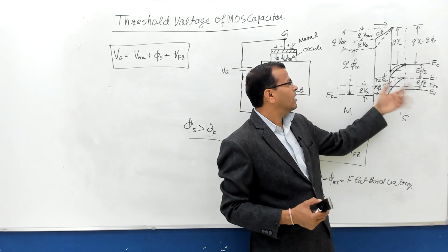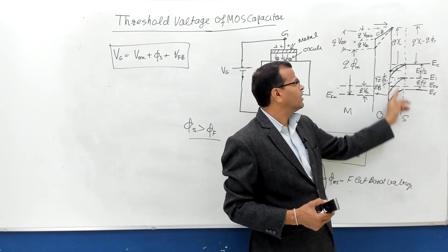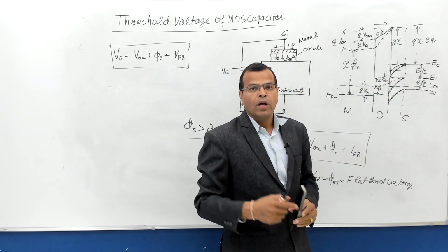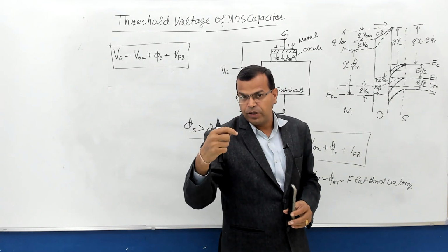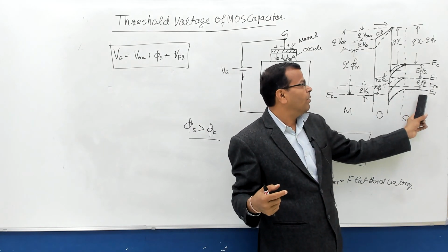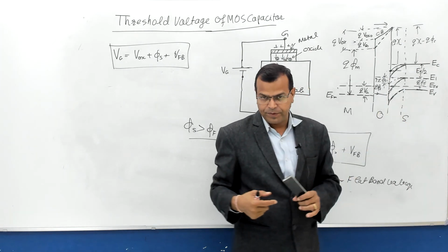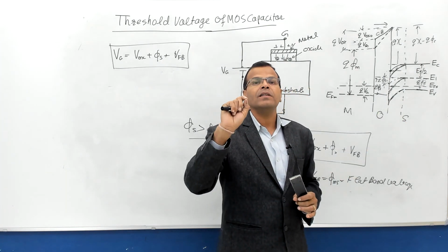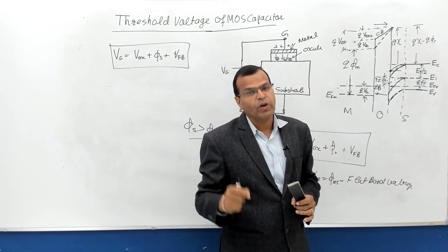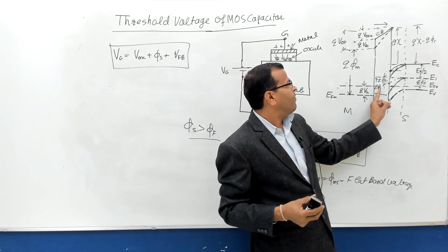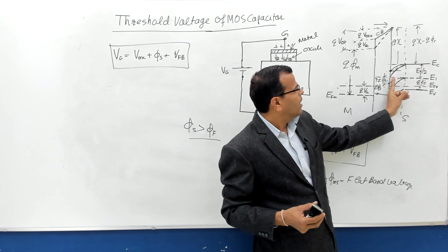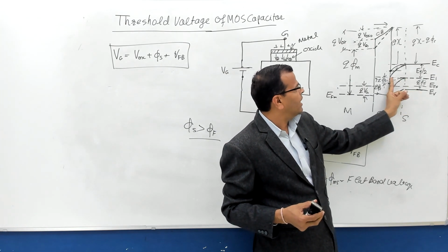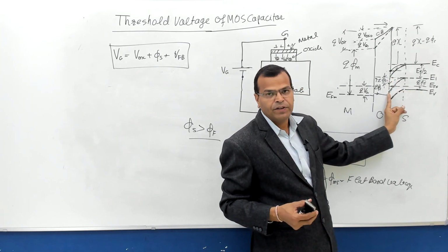In this region, but in this region, right? So that is known as inversion of the nature of the material from p-type to n-type. But there is a threshold condition. What is the threshold condition? When phi s is what? That is the fall in the intrinsic level from the steady state level to the actual level at the surface.